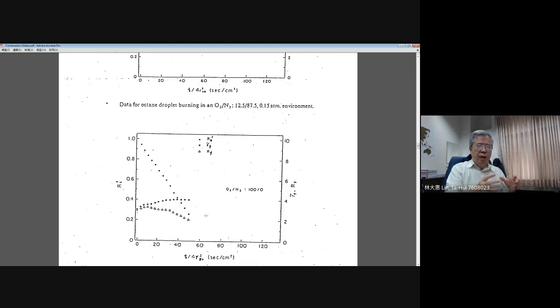This is one thing. The other thing is that in this very efficient burning process, the droplets evaporate very fast, so the droplet surface reduces very fast. By these two effects, the standoff distance between the flame position and the liquid surface reduces very fast. And here they tell you that in the final periods the standoff distance is almost fixed.